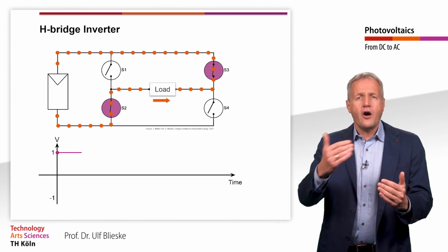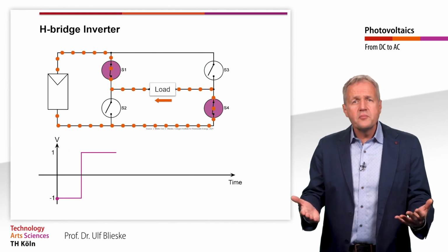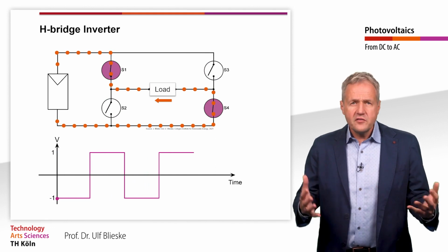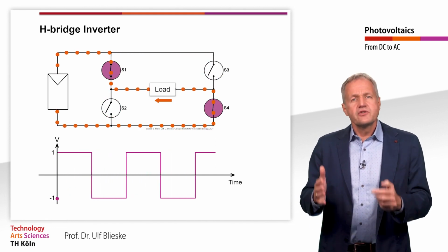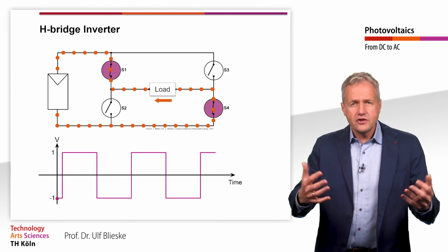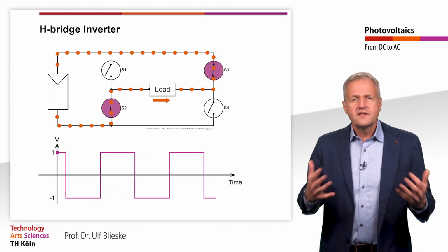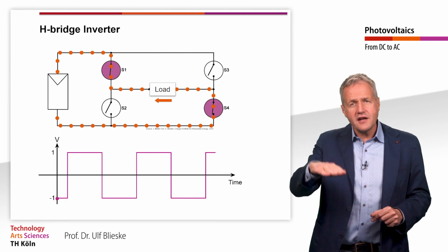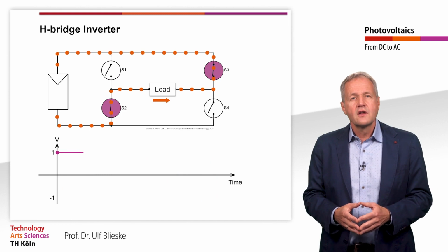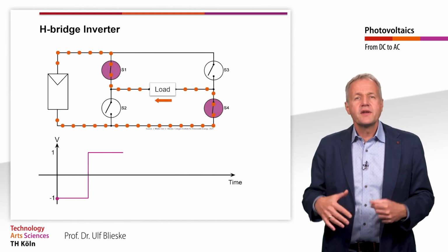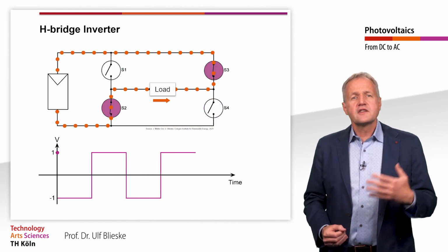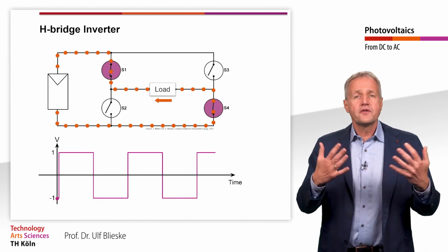This reversal of direction can also be observed on an oscilloscope. For this purpose, the voltage between the input and output of the load is measured continuously. We see that a square shape alternating current is generated by this circuit. This square wave signal repeats itself continuously. The number of times it is repeated per second is called frequency.